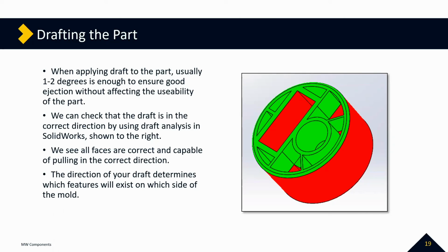And so that specific grade from whichever material supplier will have a technical data sheet, as I mentioned during the draft angle question. And that technical data sheet has the percentage shrinkage, usually around 0.5 to 1% shrinkage around there. It can be greater or less, depending on a number of factors to deal with the chemistry of your plastic. But you can take that number, let's say 1% shrinkage, and actually just more or less scale up your model.